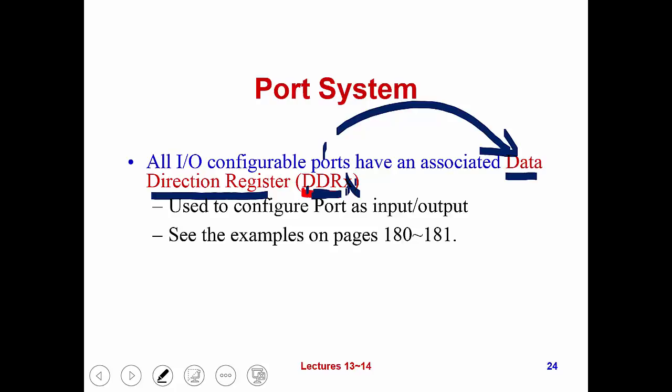To have all the eight pins or channels serve as output pins or output channels, in other words, let me show you how to configure the port C pins to output data by setting the corresponding data direction register for port C. The name of the port C data direction register here is DDRC. Because we'll talk about the data direction register for port C,